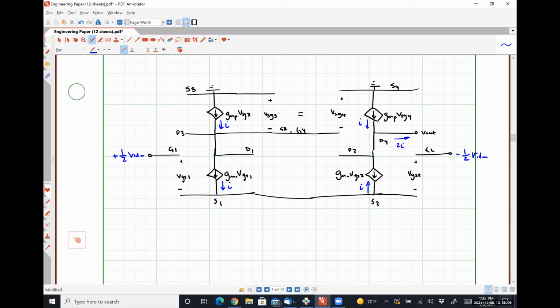This is the beauty and genius of this scheme, right? It's this twice i that lets us get twice the gain of one of these single common source amplifier stages, right? So it's how we get the same gain as the double-ended output, even though we only have a single-ended system, okay? And we'll get into the ludicrous amount of math that makes that work on Wednesday, as an introduction to real deal op-amp analysis. All right, any questions from today?